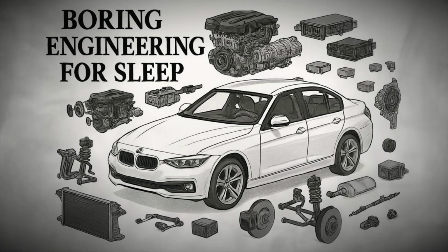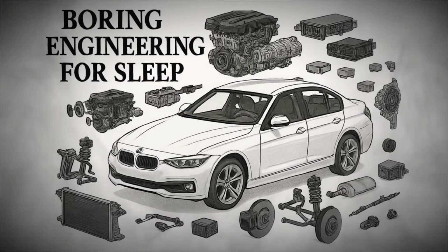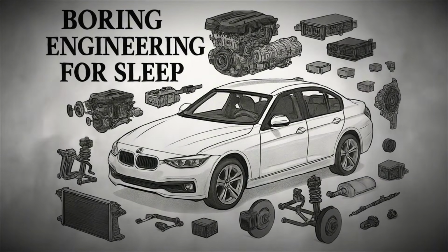Emission control extends beyond the catalytic converter and filter, as modern cars use oxygen sensors placed in the exhaust stream to monitor the composition of gases. These sensors send signals to the engine control unit, which adjusts the fuel mixture to ensure combustion remains as clean and efficient as possible. This closed-loop system allows continuous regulation and is critical for meeting environmental regulations.